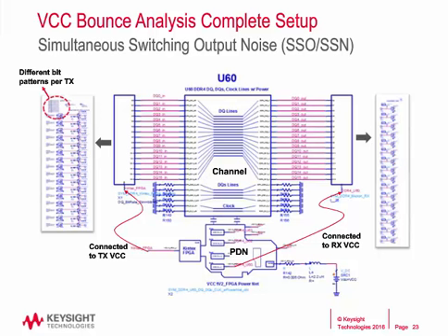Data pattern per each DQ line must be different. So, as you see in this schematic view, each PRBS source is modeled with a different bit pattern to represent the different data patterns for all 16 DQ lines in this example.